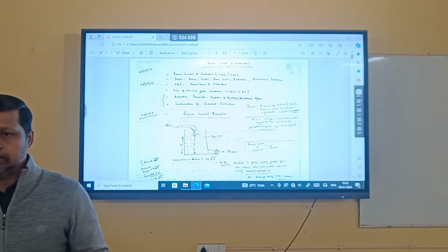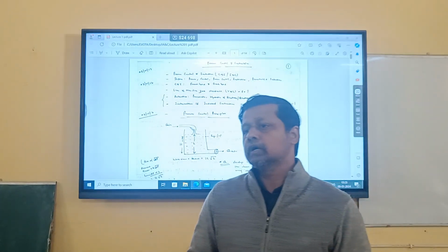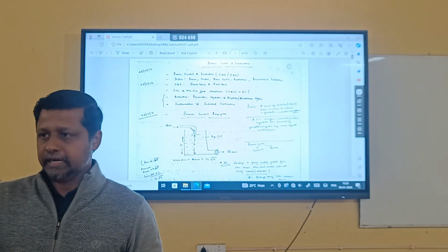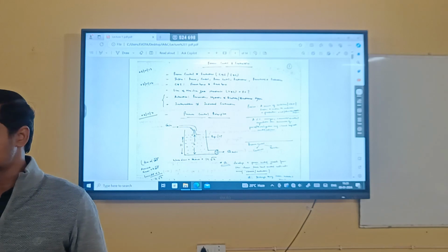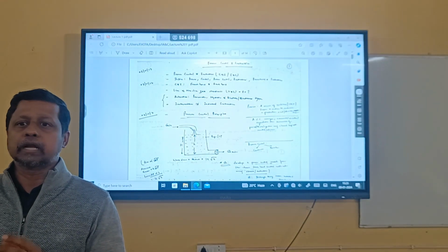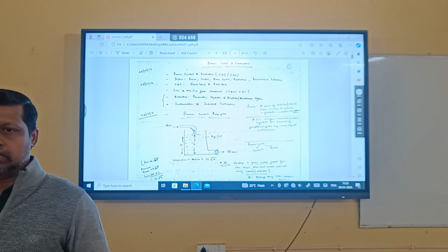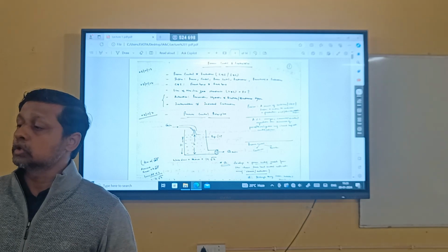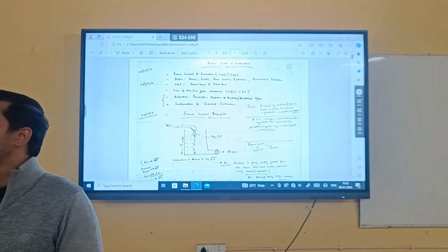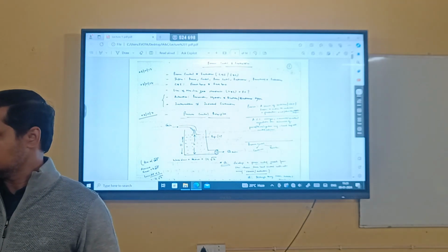Through those screens, it doesn't matter whether you have a power station or you are in a steel industry or whatever, and whatever type of control mechanism it is, whether it's SCADA or DCS, doesn't matter. You have access through those screens, those display panels, those monitoring systems, by which you are not only able to monitor those parameters, while the finished product is being manufactured on a real-time basis, but if needed, you can also regulate those parameters through the HMI, or you can say by commanding the controller. Are you getting my point?